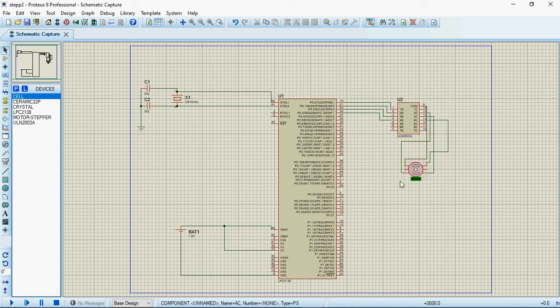Okay, and these two terminals, short them together and connect them to the motor driver supply. For the motor driver supply, you can go to generator mode. You have different sources. I'll take the DC supply and drop it down here. This is the motor supply. The value given to this motor supply can be changed, so what I'll do is just make this 12 volt.